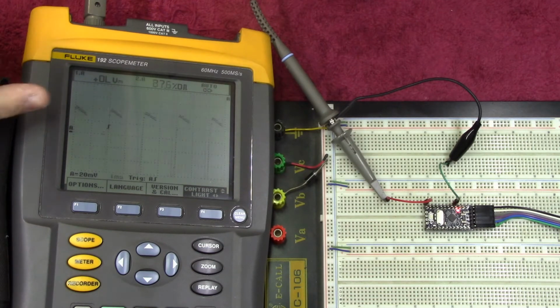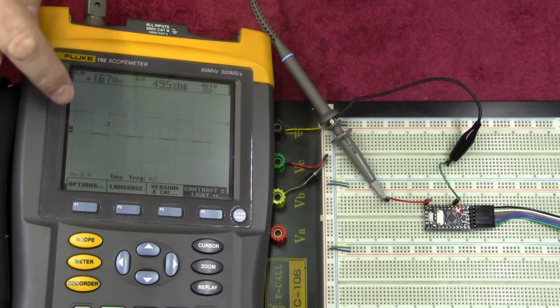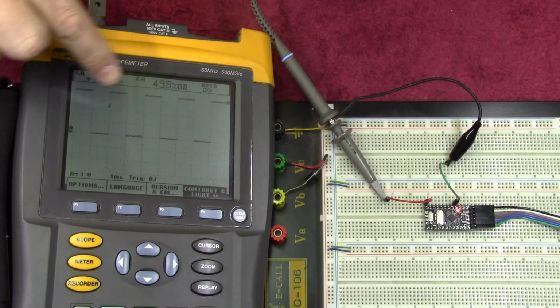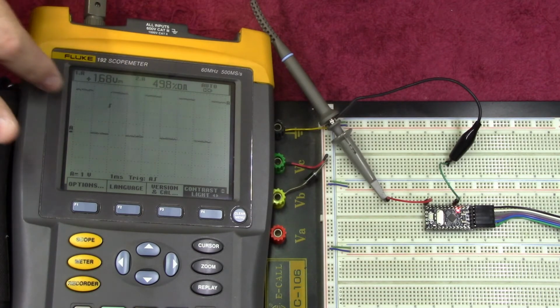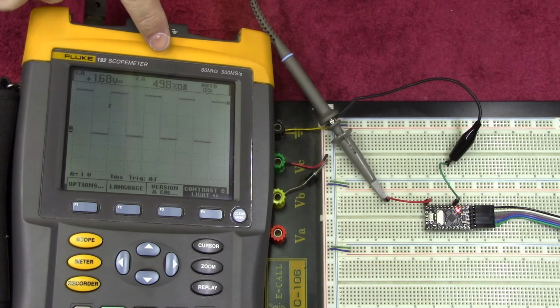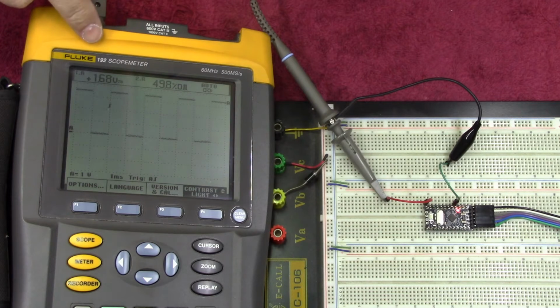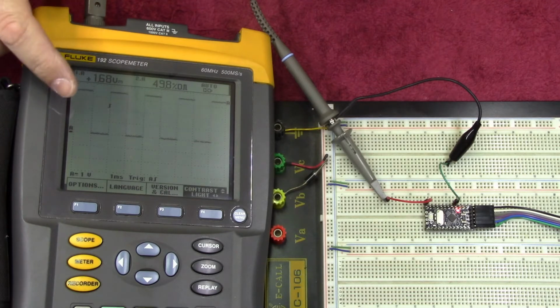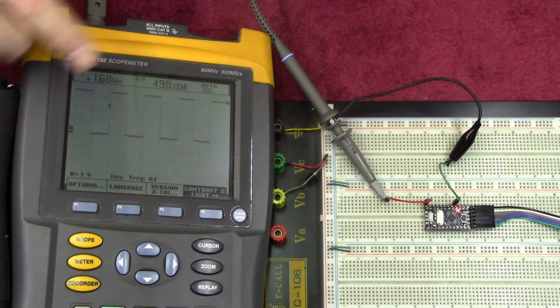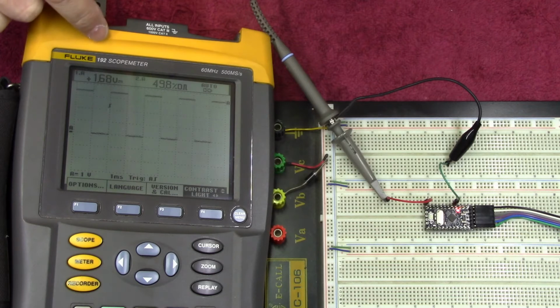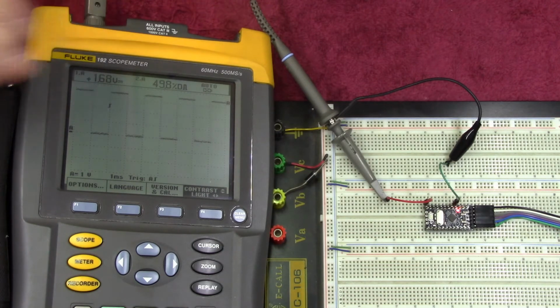Right, so we've now got a 50% duty cycle, and there we go, it's scaled up. You'll see it's still a peak of 3.3 volts, but you'll now see a 49.8% duty cycle, and your DC voltage is now 1.68. Now remember, we spoke about that halfway mark at 50%. There it is. So now you're seeing a 50% duty cycle, you're seeing the halfway DC voltage being measured, and everything is looking peachy so far.